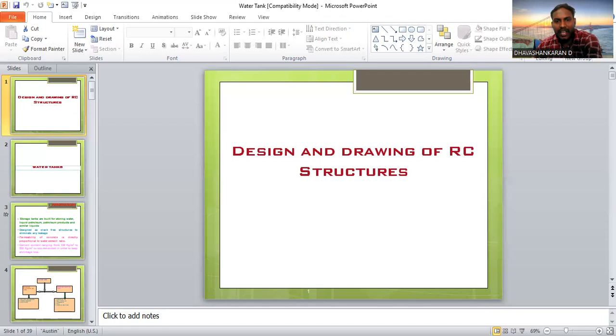It is not having any joint or any relationship; they are constructed separately, and that is called a rigid base. A flexible base is more preferable for the tank storage structure, and a rigid base is also practiced in some conditions, as per the IS code provisions.